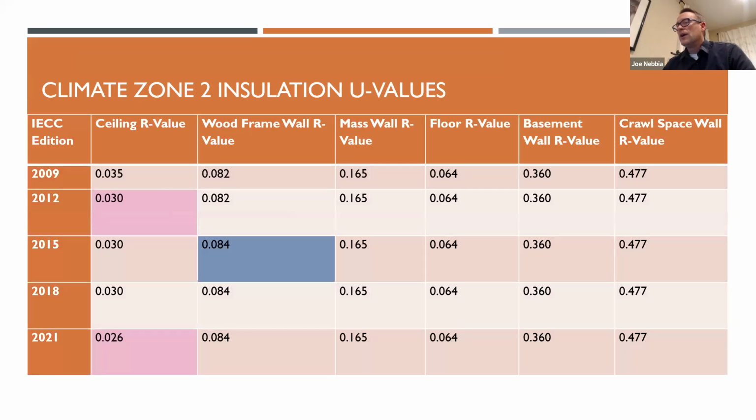For U value, again, this is where you might go if you want to do something different. One example, and you wouldn't see this often in residential construction, is maybe somebody wants to do an above deck rigid foam for roof insulation. Again, that's more of a commercial application, but maybe somebody wants to do it, or a SIP roof or something like that.